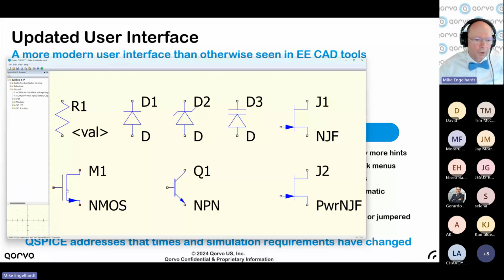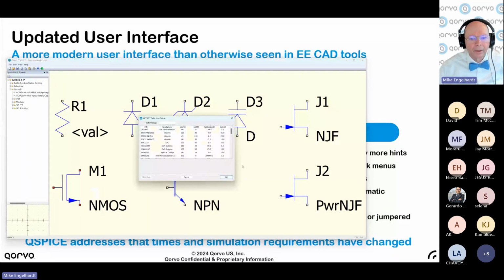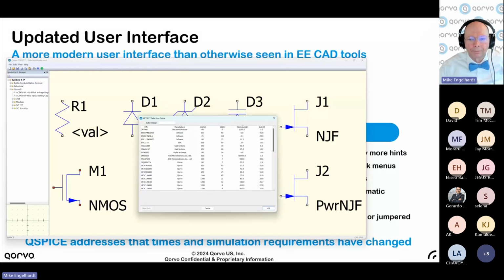For a MOSFET is where you see it really starts getting valuable. So in MOSFETs, you'd like to be able to sort them by RDS on. But these RDS-ons are basically the rating from the datasheet of that part, and some MOSFETs are intended to be logic level, and some are intended to use with a much higher gate voltage. To be fair, you should probably sort them by the way the FET is meant to be used.